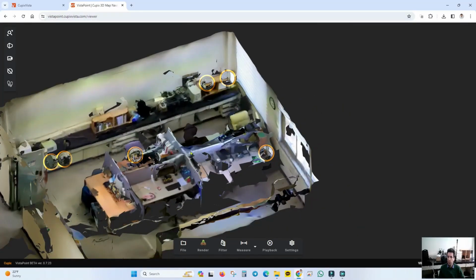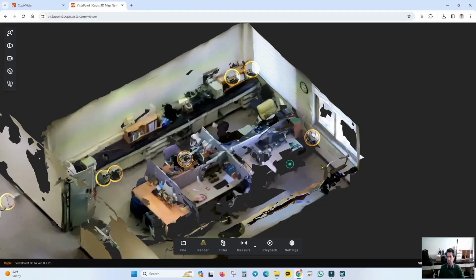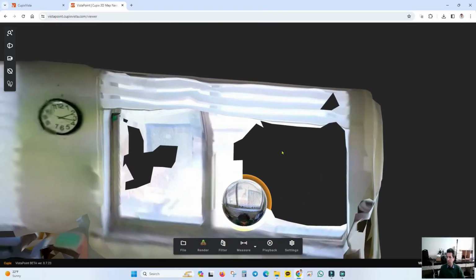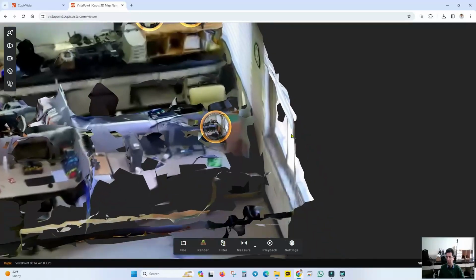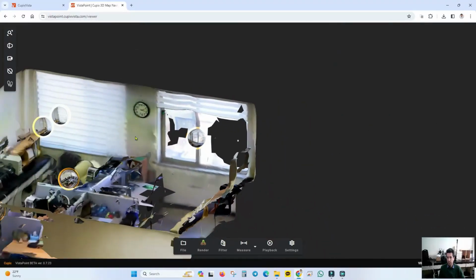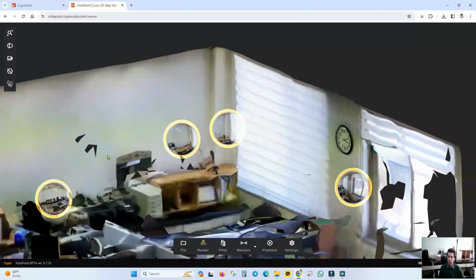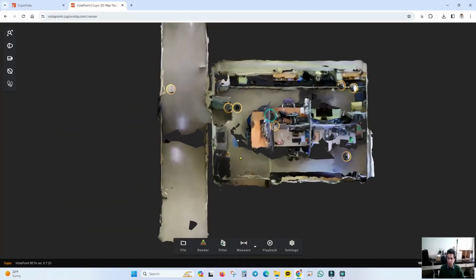However, in photogrammetry, when we want to do this manually, we have to remove it ourselves by hand, which takes extra work. And even after we've deleted those meshes, it leaves a hole like this, and we can't replace it with anything. Repairing the 3D model isn't that simple, and it's very time consuming and labor intensive. So it's better for us to be careful from the very beginning and scan the space correctly, so we don't have to spend time on post-processing. Let's move on to downloading this file.